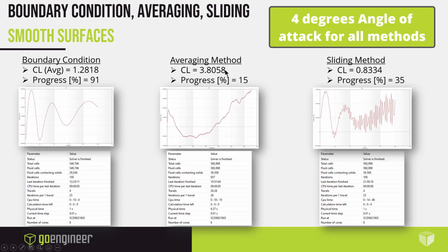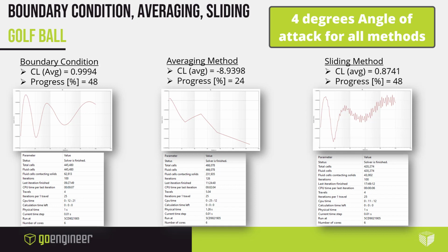All right, so this lift coefficient is significantly high, and I ran all these at 4 degrees angle of attack, which I don't know if you recall that from the previous slide, that's way too high of a lift coefficient. These are probably closer to reality for the lift coefficient of this. This is going to be the NACA 0015 at an angle of attack of 4 degrees at a Reynolds number of 50,000.